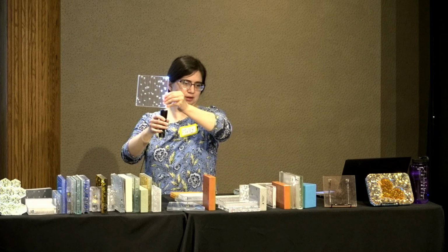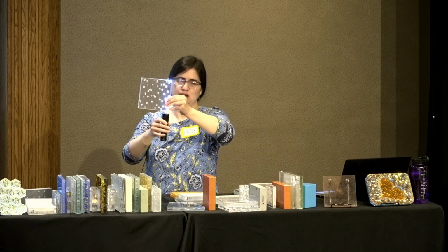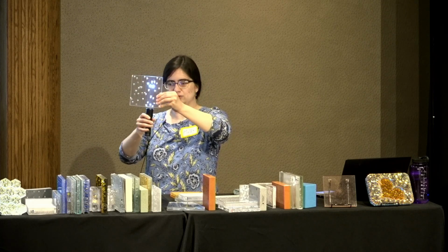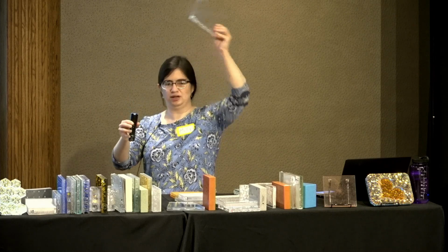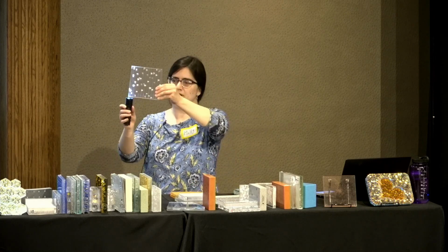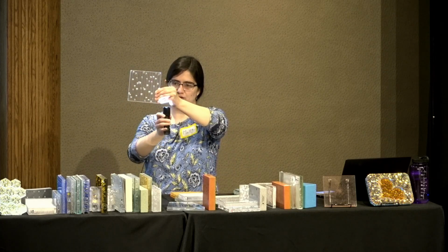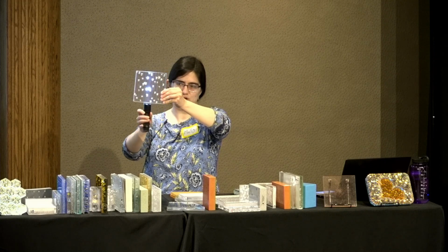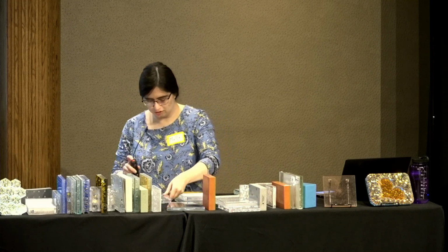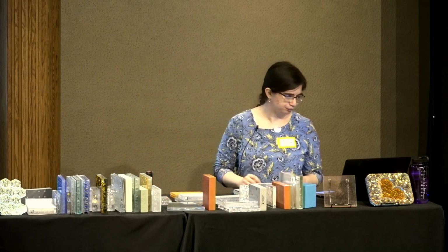You install this big, heavy 10-foot panel. 10 years down the line, the LEDs finally go out. You don't have to take the panel off and disassemble the whole thing. You can just slide the lights out because they're just resting underneath. So, ease of access and maintenance.